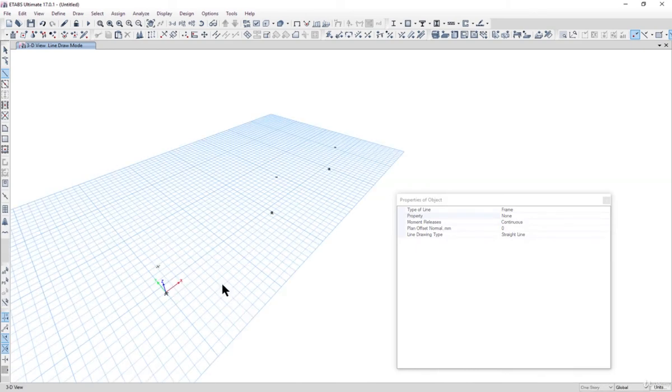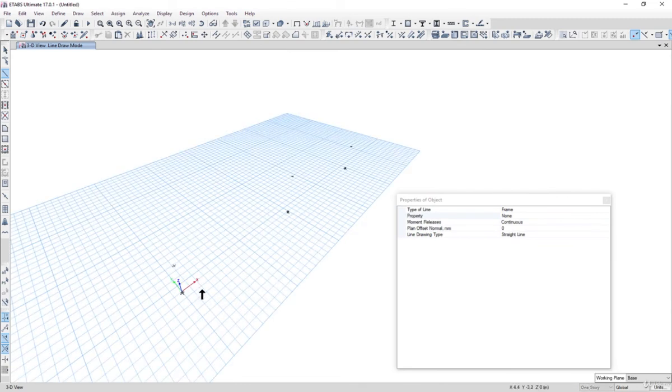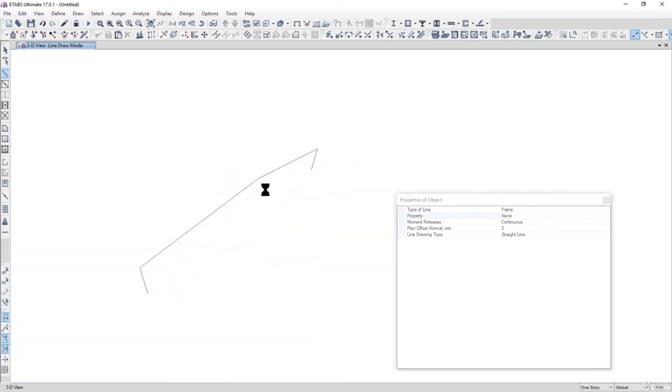So you can press the scroll wheel on your screen and then move left or right so that it automatically snaps to the joint. So left click here and then again left click here. Left click here. Here you can see the distance is 20 meters as expected, and left click here, again the distance is 20 meter. Draw a column here, right click, and then draw a beam from this point to draw a column from this point to this point.